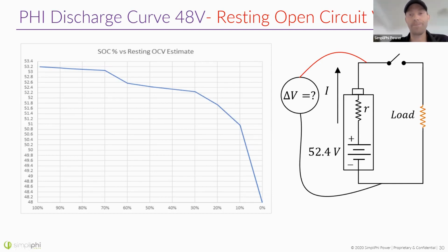I made a little figure on the right, and it's to give us something to think about as the battery is discharging. When a load is being powered, all batteries have a little bit of what's called internal resistance. This comes from the BMS, it comes from the battery cells themselves, it comes from actually the migration of the lithium through the battery cells. There's an internal resistance. So if the battery voltage is 52.4 volts in an open circuit condition, if the switch is closed and we're actually powering a load so that a current is flowing through this circuit.